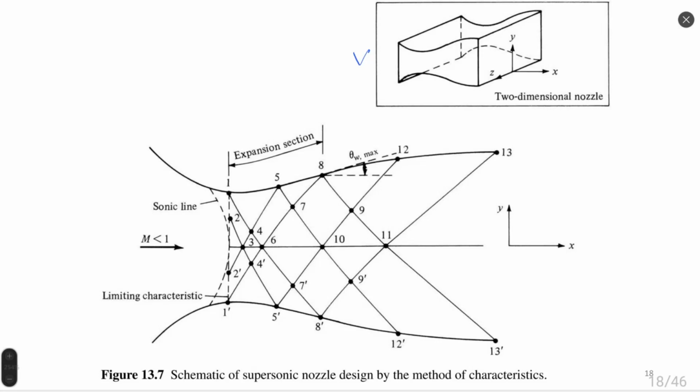Okay. If you would like to calculate a nozzle or axisymmetric rotational body, you need to use a similar model, but for axisymmetric flows. Why is it not present in the book is another question you may ask. The answer is simple: instead of solving just algebraic equations for the Prandtl-Meyer function and characteristic line direction, we need to solve a differential equation at each point. And from a didactic point of view, it becomes heavier and not possible to visualize and show by the simple Prandtl-Meyer function Mach angle relation. The direction of the characteristic line would be calculated from an ordinary differential equation. It is not difficult. It is relatively simple.